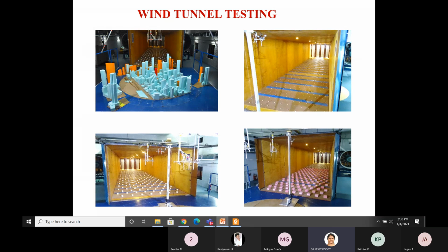In our university, there is a wind engineering department, but that wind tunnel is different from the structural wind tunnel, because for us the building has to be our building. For a structural setup it will be different, because our structure is a cantilever structure. Whereas in aeronautical engineering, the specimen will be horizontal, because they have to test the aeroplane in the horizontal mode, but for us the building is in the vertical mode. So there will be a slight difference between the aerodynamic wind tunnel and the structural one.